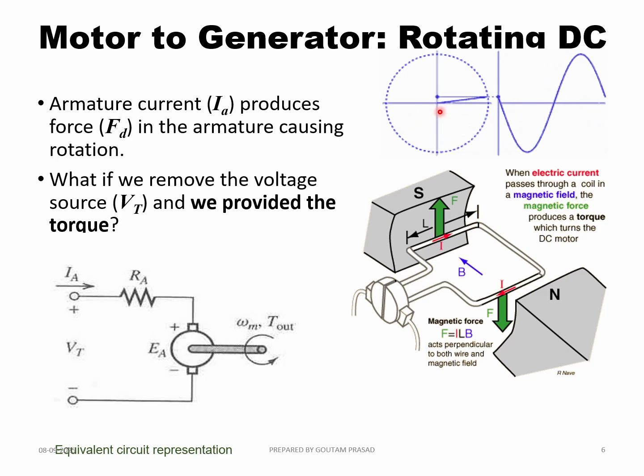So here I have tried to show you the phasor diagram and the output waveform of the AC we are getting as the resultant. If you move this armature with the help of a prime mover in the clockwise or anti-clockwise direction, the EMF is induced in the conductors of the armature, and that reflects between the two terminals of this generator.